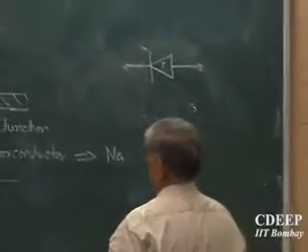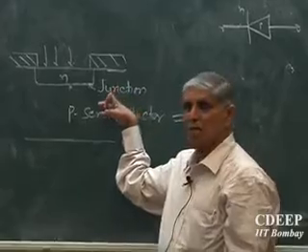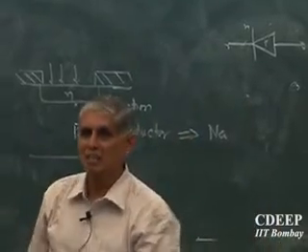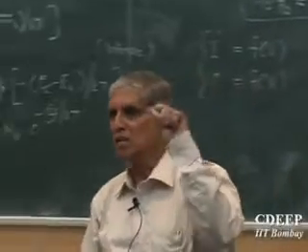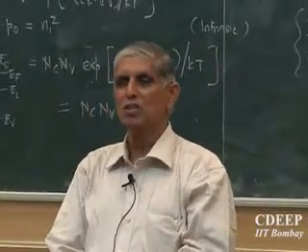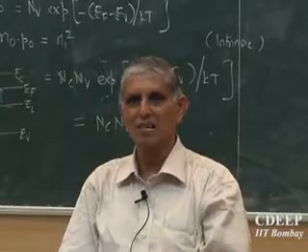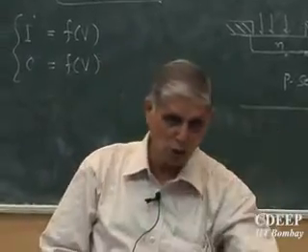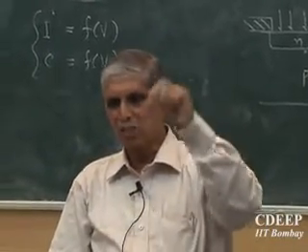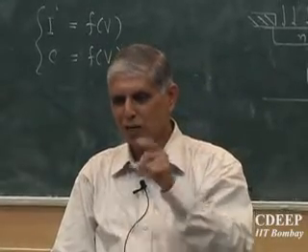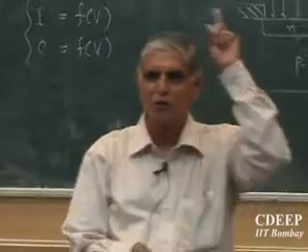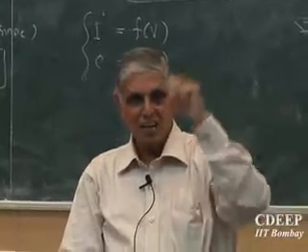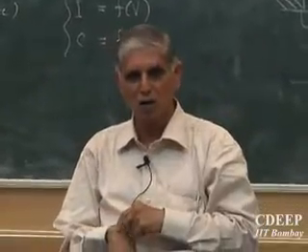Now here is the issue. This material initially was P-type. If I start putting N-type dopant inside, what will happen? N will create electrons, P has certain holes, so these electrons start to recombine. Whichever area I am pushing the impurities into, N will first start compensating. So any number of donors I put in initially will compensate the earlier ones, because of the recombination going on.